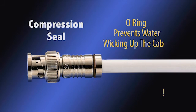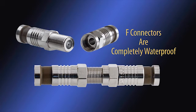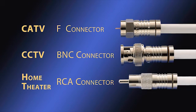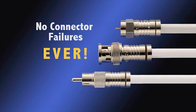The connector also has an internal O-ring to seal the mating surface from water wicking up the cable. A properly mated pair of F connectors are completely waterproof. They have been tested in a 3-foot head of water. The concept was to develop a line of products that could be used by the installer for the CATV, CCTV, and home theater systems markets, using one assembly procedure and one crimp tool for F connectors, RCAs, and BNC connectors. This connector will cost more than the previously discussed items, but there will never be a service call as a result of a connector pulling off the cable.